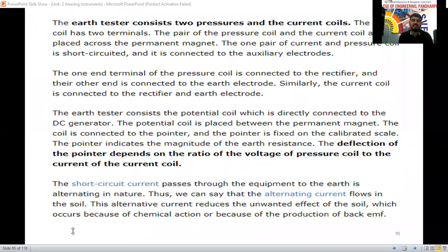You are studying electrical engineering, so you should know the benefit of earthing and what is useful about it. Even in your area, if there are hotels, lodgings, or tourist places, you have to suggest it. If an earthing pit is provided in your house, you have to ask what the resistance of that earthing is and check it. If there are electrical auditors, they will check only this: whether the electrical earthing is done or not. If it is done, then what is the resistance of that earthing pit? They have to check maintenance.